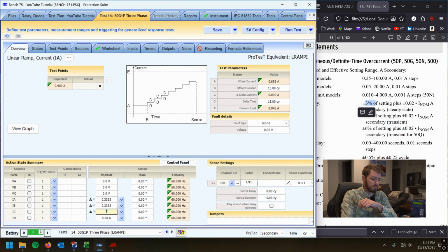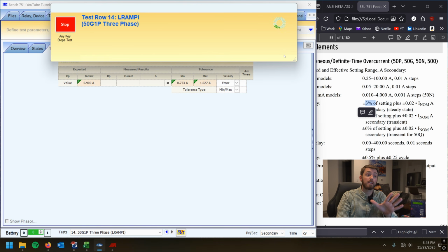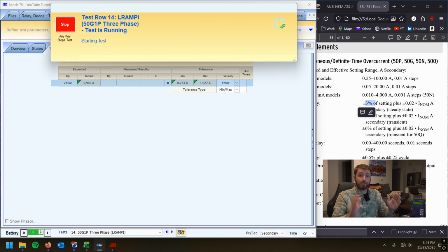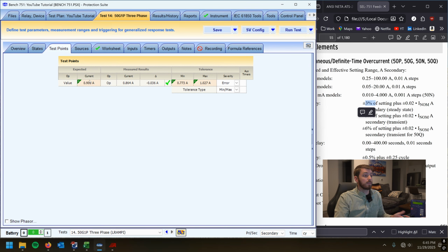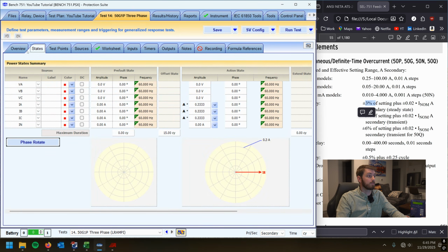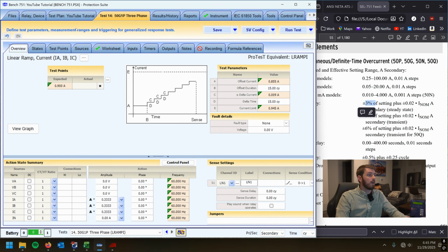As much as we can, 0.33333. And then we should be able to run this and get the same result, but I'm measuring it by doing 3 phases of zero sequence current instead of 1 phase of current on an unbalanced load, right? And look at that, we got the same exact result as we did before. That's great, that's totally what I expected. Wink, wink, totally didn't expect that to work. Just kidding, I knew it was gonna work.